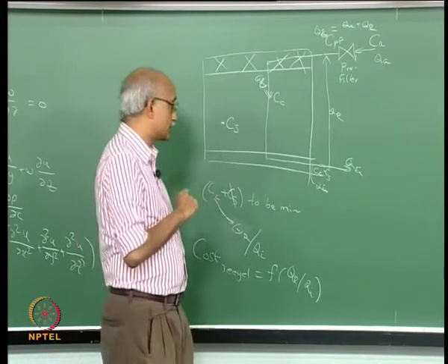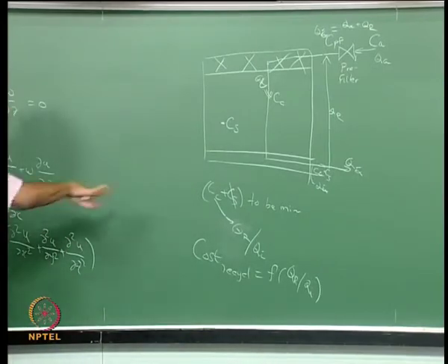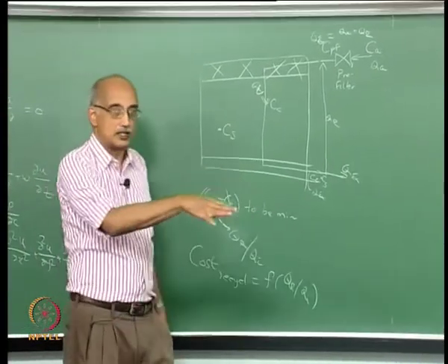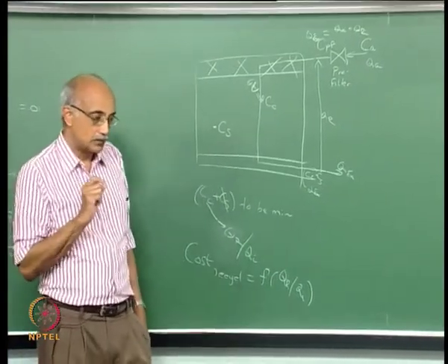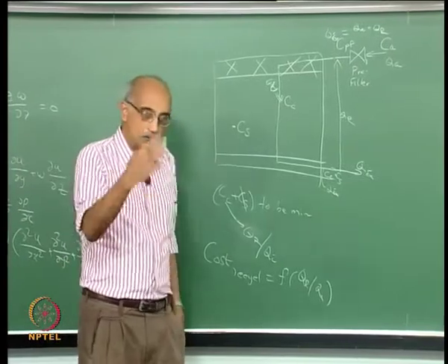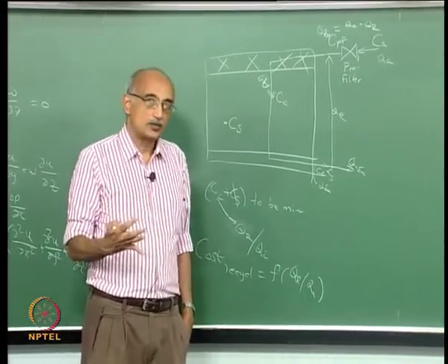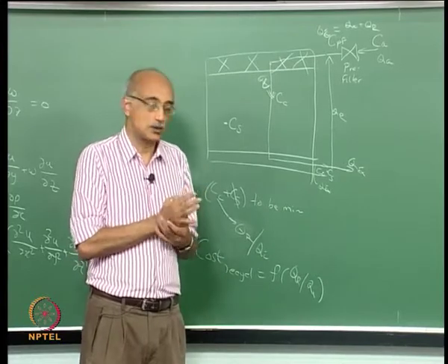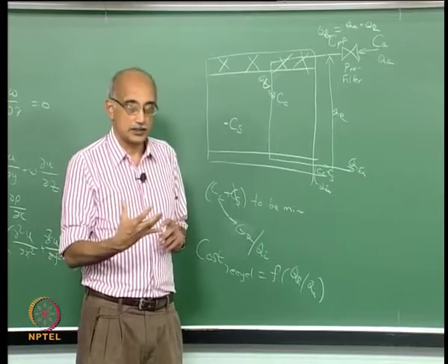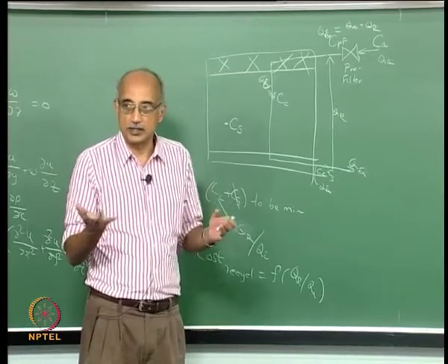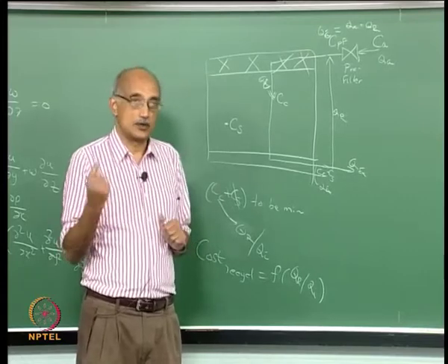Now the other thing also you have to keep in mind is when you solve the Navier-Stokes equations or even the simplified quasi-steady model, what you're really getting is a picture of how airflow is developing over the clean room, and if you solve the two-phase model, you can also get a description of particle velocities inside the clean room. You'll get a distribution of particle velocities, but from that you have to extract particle deposition rates.